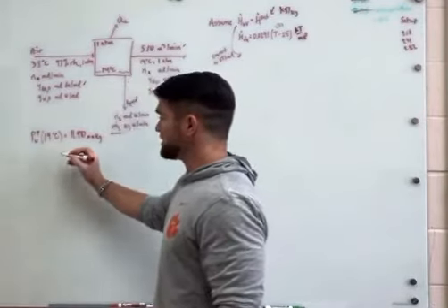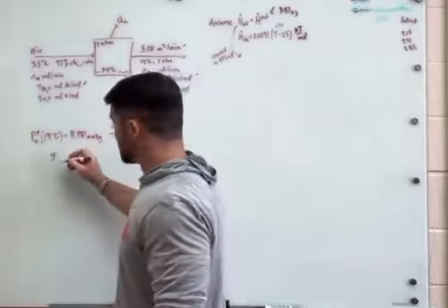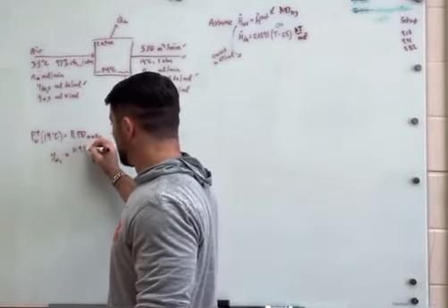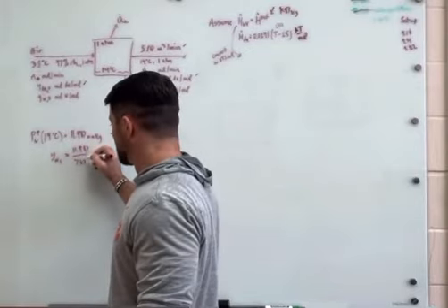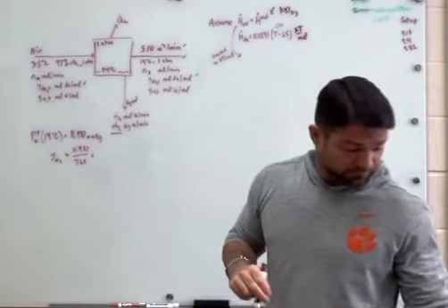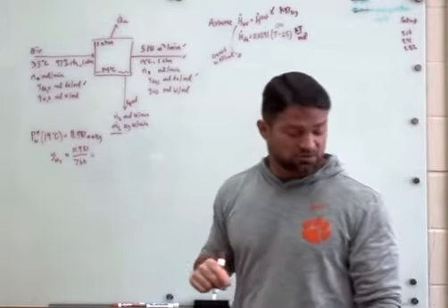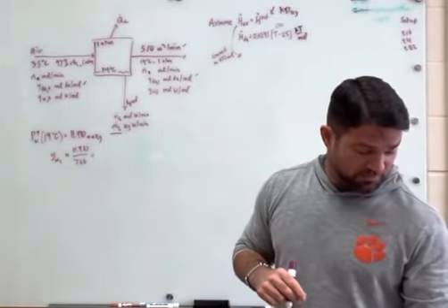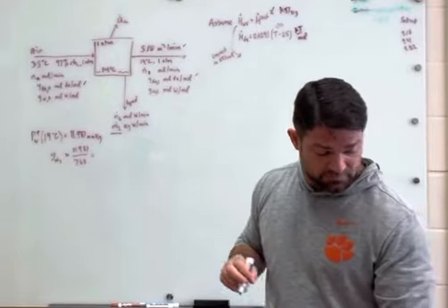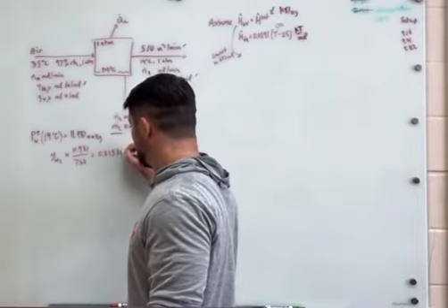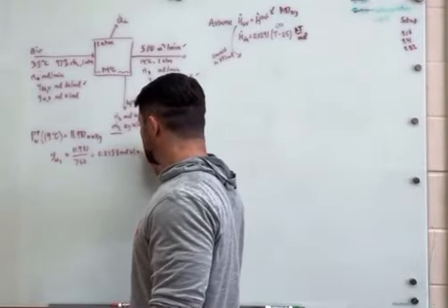So the mole fraction of water coming out is just 11.987 divided by 760, because the partial pressure of water is equal to the saturation pressure of water since it's in vapor-liquid equilibrium. This gives a composition of 0.0158 mole water per mole.